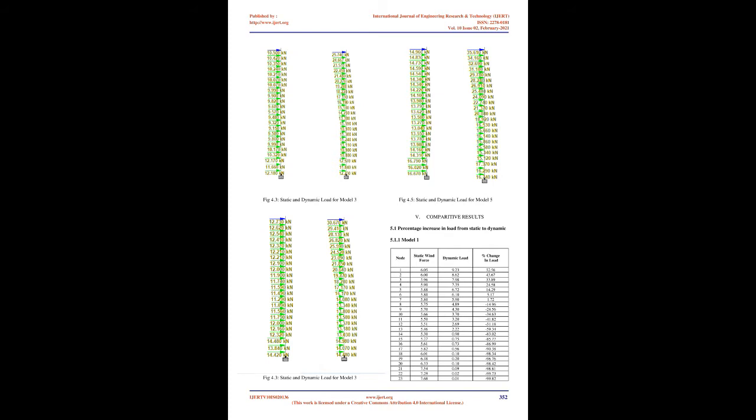This paper deals with the analysis of 3 chimneys of 5 m height designed as per IS 6533-1989, and wind loads were calculated as per IS 875-1987. The wind speeds considered were 47 m/s, 50 m/s, 55 m/s, and the static force, dynamic forces, static moment, and thickness of those chimney shells are compared.